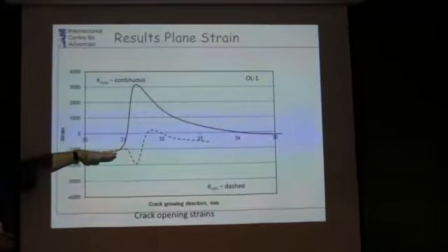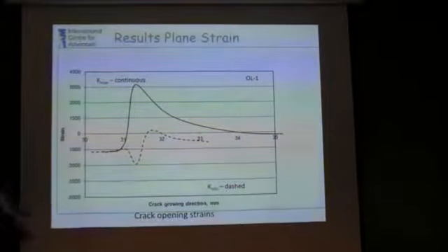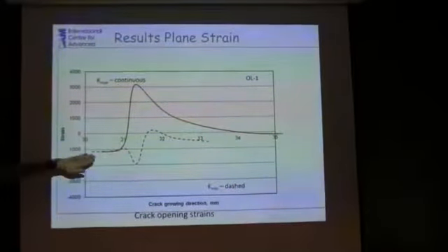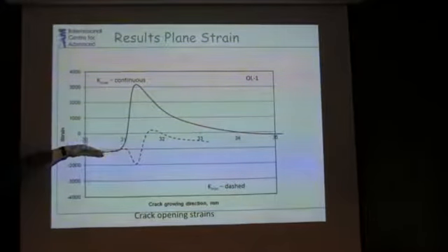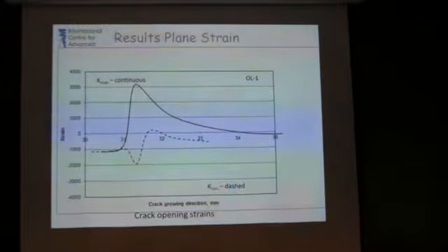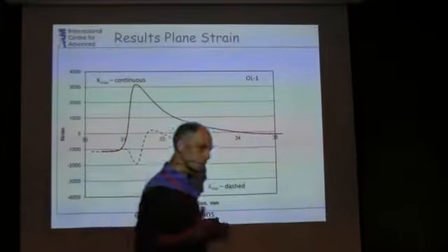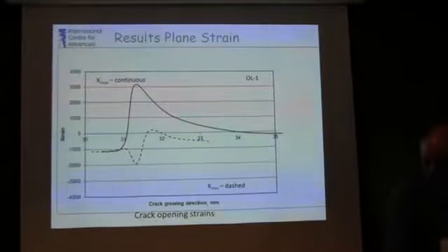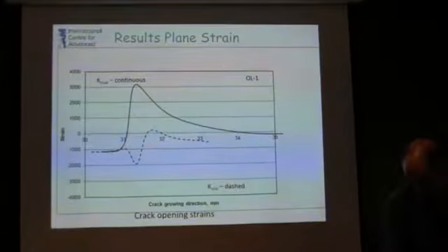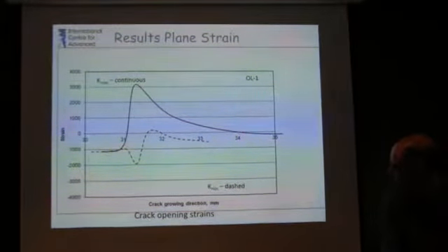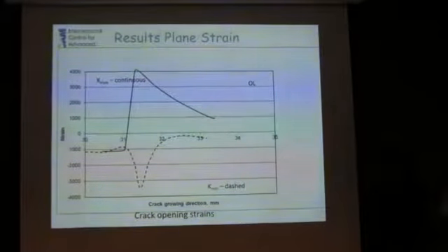I think there's an offset on this data, which relates to our stress-free lattice spacing, which is probably a little bit out, but you can see that we get a negative stress along the crack, which I don't think is a Poisson's ratio effect. I think it might be a bit of a Poisson's ratio effect, but I think it's a little bit that we've made a little bit of an error in our stress-free lattice spacing.